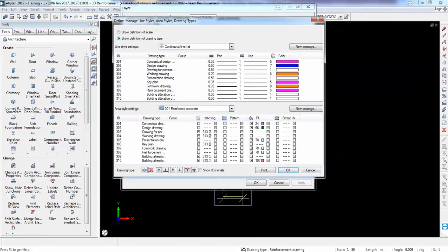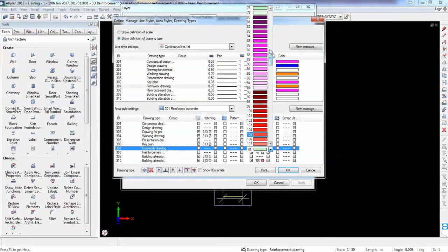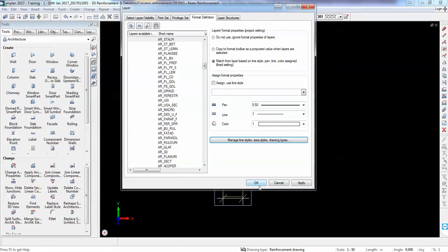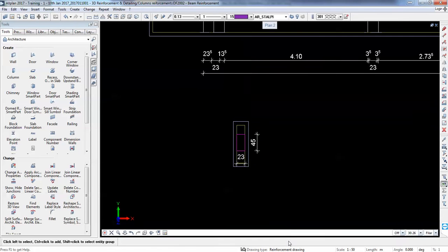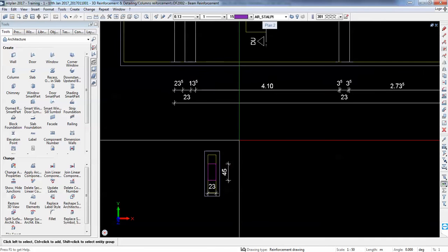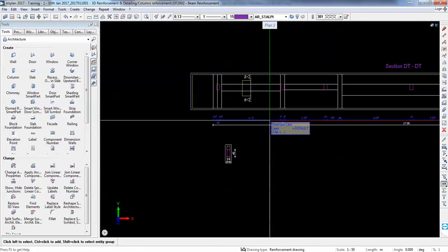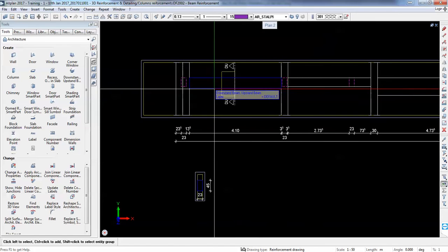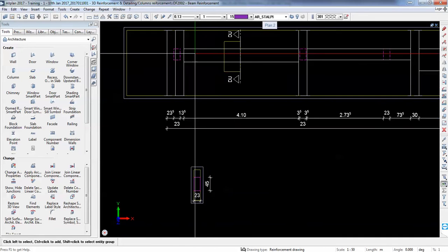So it's just the definitions that I can set for how the elements should look on each type of drawing that I create. For instance, for a formwork drawing, I can choose it to be darker, and for reinforcement to contain nothing. In this way, you can work with architects, or even inside your own office, you can just choose the type of drawing you are creating. So there's no need to remove or add hatches. Okay, so this is how I remove the lines.